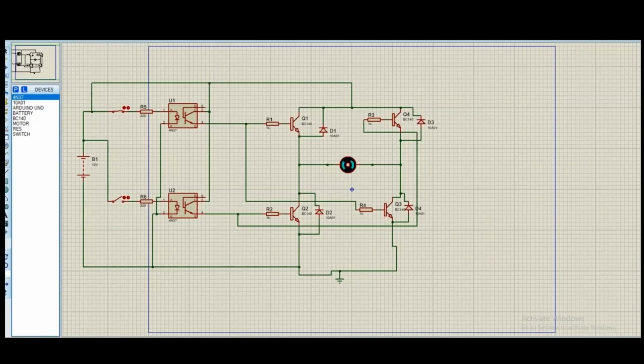And then if I open this switch, this upper optocoupler is in the on state, like its LED is now on, and this phototransistor is now working. But when I turn this switch off and this switch on, something similar happens in the lower circuit.